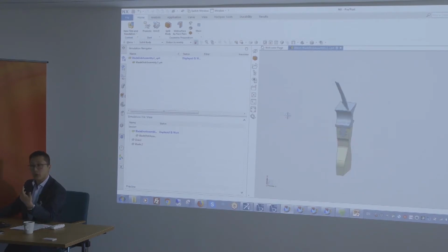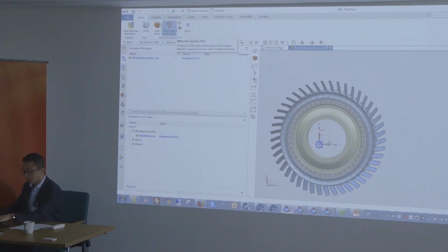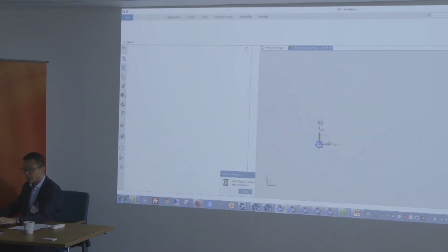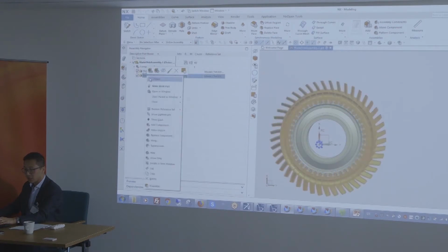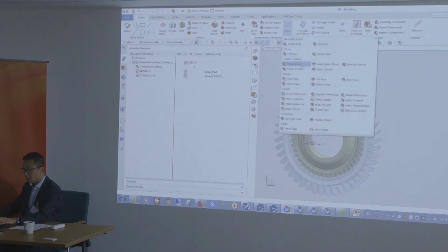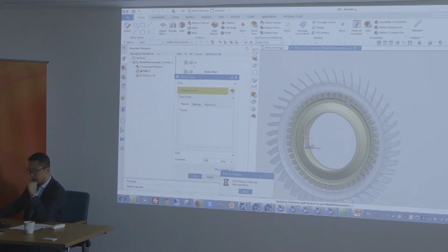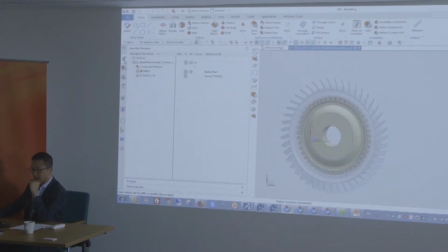But then if you save your model and the analyst decides to make a change, you don't want it to modify the geometry, and that's your original geometry here. So if the analyst decides to change again that dimension of the disk, we can always go there, make the work part, resize the face, change this to 150. Let's make it drastic, 100 millimeters. Okay, so that's a change done by the designer.